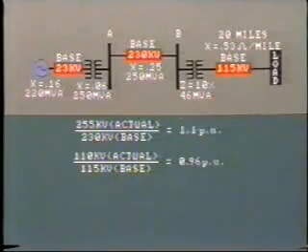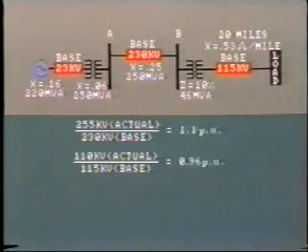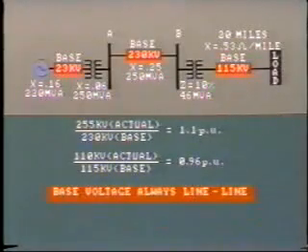So you can see another advantage to using per unit quantities. Under normal operating conditions, all system voltages are close to 1 per unit, so errors in the calculations and system abnormalities are easier to spot. It is important to remember that the base voltage always indicates three-phase line-to-line volts, not line-to-neutral.